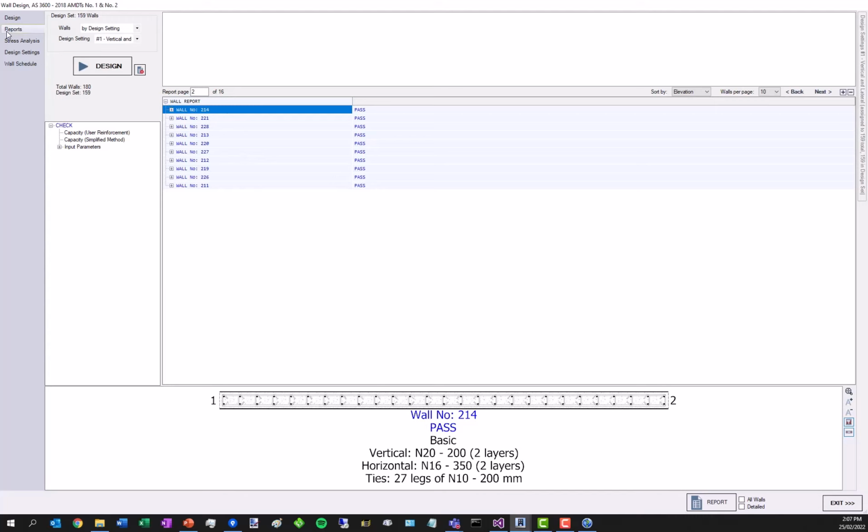In this tab, it opens a report, shows the section, shows the wall in section, plotting any reinforcement that was designed, any ties if they are required. If there were boundary elements, if there were critical tension reinforcement zones, we would see them here as well, but currently none. Let's expand the report out. Let's see what we see.